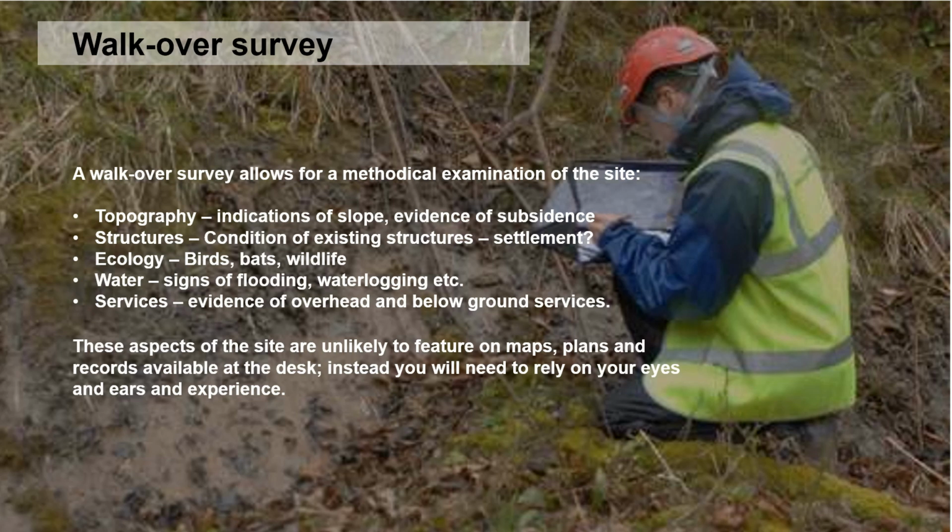So are there any manholes or power lines or such? And if we consider these aspects, some of them may feature on maps, some of them may not, but a walkover site will give you first-hand experience of their condition and will give you clues as to how best to develop your own proposals.